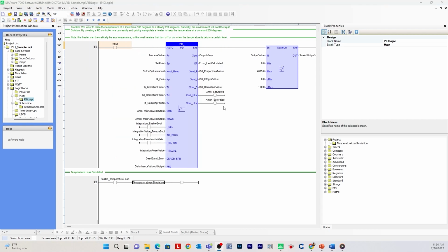One, the proportional gain. The higher the proportional gain value, the faster the controller responds. If the proportional gain is too low, the controller reaction speed will be too slow, and it may not be stable at that point. Too high, the controller may overshoot and start oscillating.